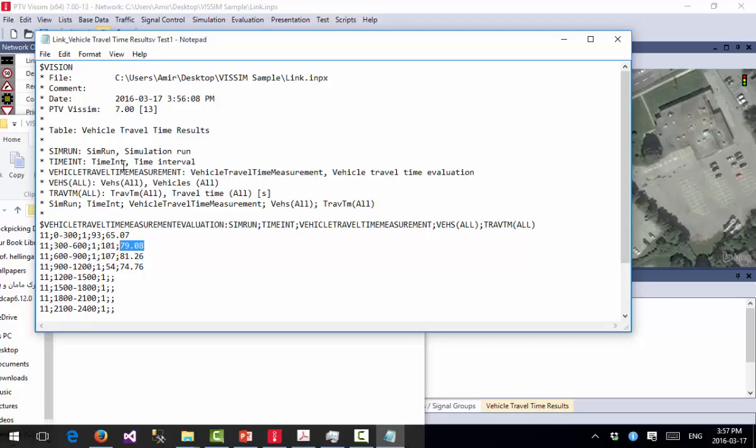For example, maybe in your assignment, one of the questions is to draw the travel time for this segment of the road over the simulation period. Then you will just extract this information, define the travel time study area, and collect that information from there. Or you want to draw a Greenfield model, and you want to extract the volume density feature.